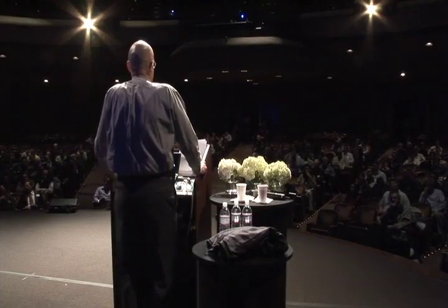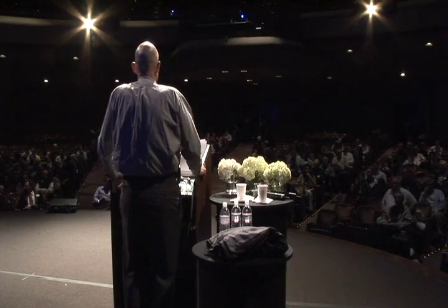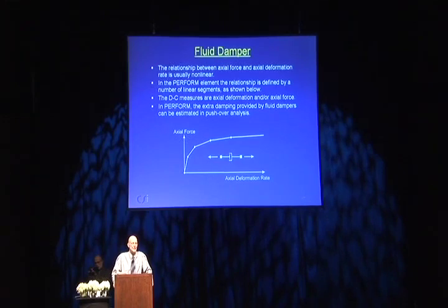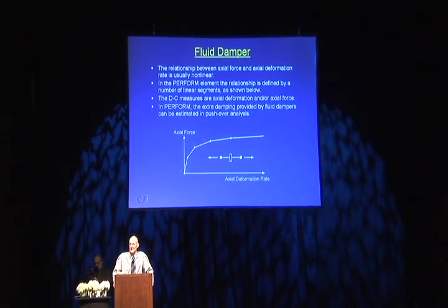Incidentally, if you do a pushover analysis, there's no dynamic effect, and so if you have a fluid damper, it doesn't do anything. It has no stiffness in the pushover analysis. But Perform does have a little feature where you can estimate the extra damping provided by fluid dampers. Even though the pushover analysis doesn't have any strength from the fluid dampers, it has an approximate method which will estimate the energy dissipation in those fluid dampers and give you some rough idea of how much additional damping you would get.